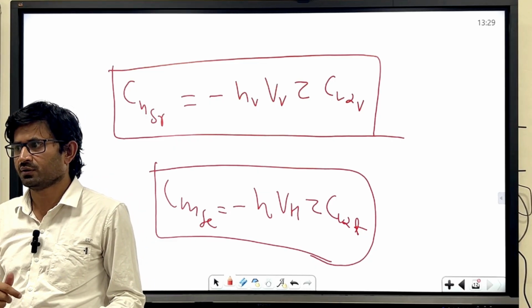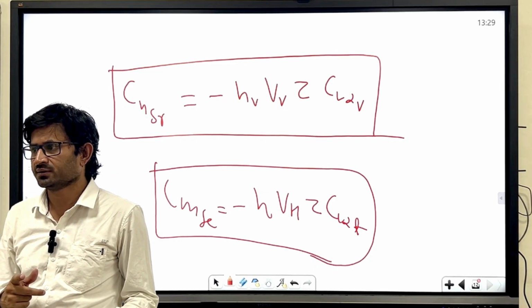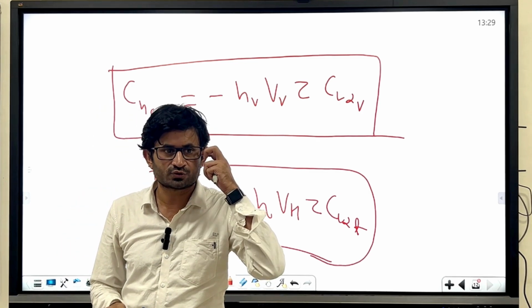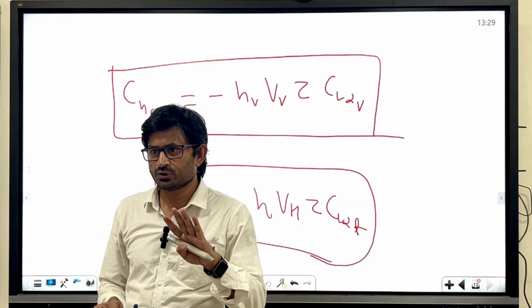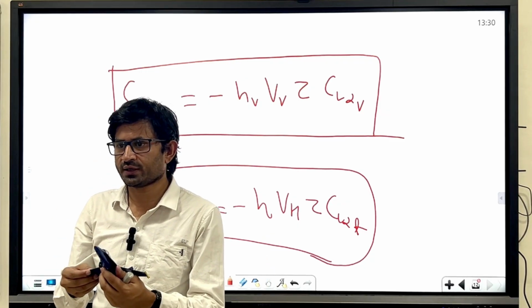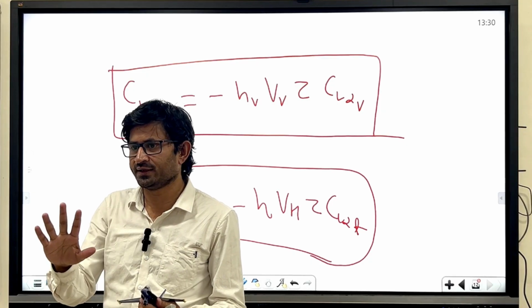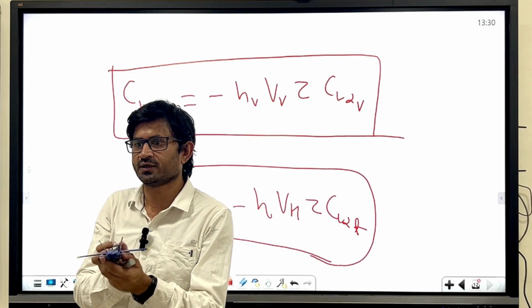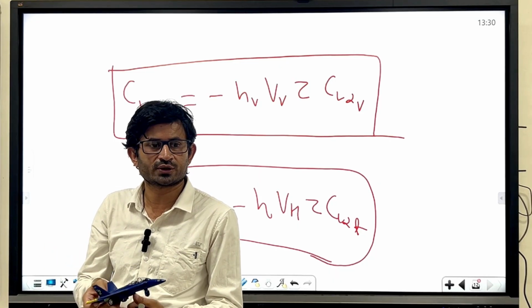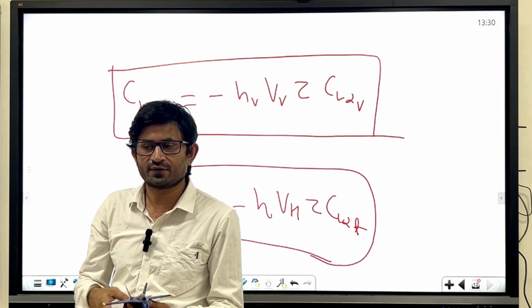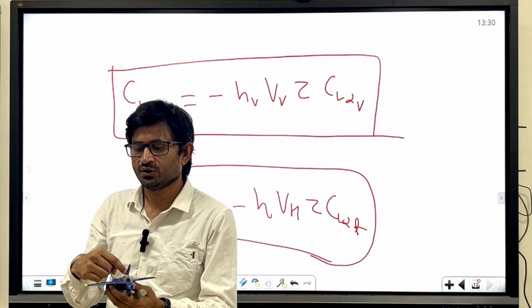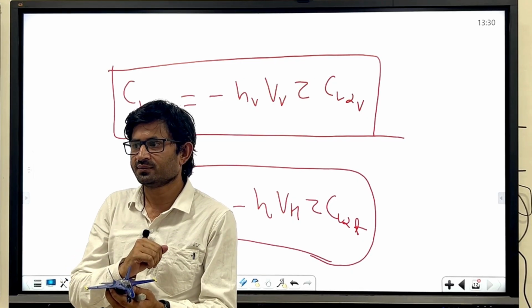So in this case also, you are using the rudder at an asymmetric thrust condition. One engine fails or one engine is partially working, not producing the thrust as you want, less thrust. In that case you can use the rudder. Another case: your aircraft is stalled, so you are not producing any lift and you are losing altitude, and at the same time you are yawing, and that yaw rate is more than the roll and pitch rate. That phenomenon is known as a spin. So in this case, to stop the spin, you can use the rudder.